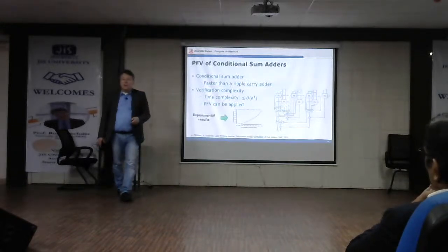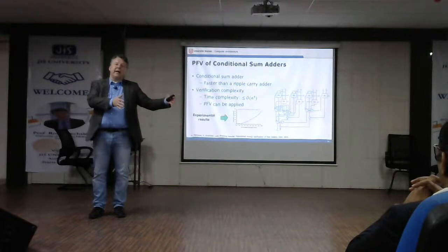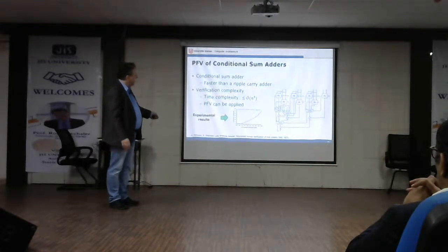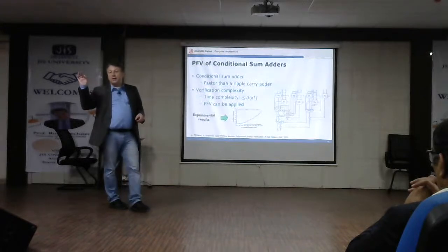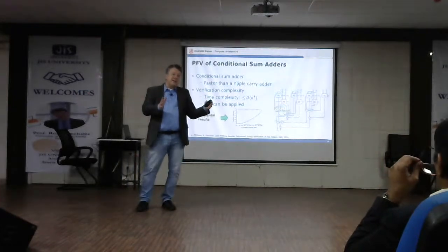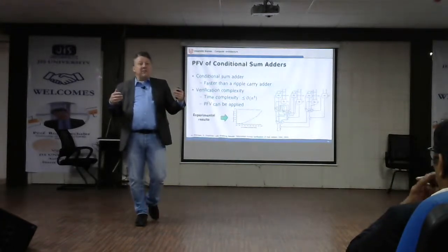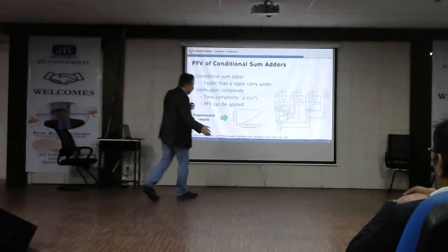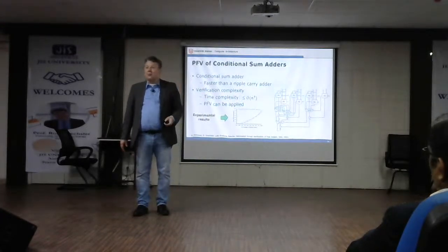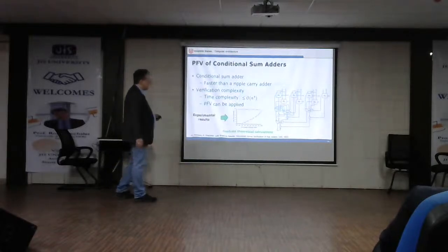And now experimental results show that, you remember, we had this for multipliers, we had 4-bit, 8-bit, 16 bits, and then it explodes. Here now we can do 1,000 bits in no time. We can calculate 10,000 bits in 200-300 seconds. So these are really scalable approaches, because nowadays it is still that often the design people are ahead of the verification people. You have difficulties in verifying 64-bit designs, but so far not many people are building 10,000-bit designs. So that is more the next generation. In cryptography, we sometimes have 1,000 bits or so, but this is really rare. So this also confirms the theoretical calculations.